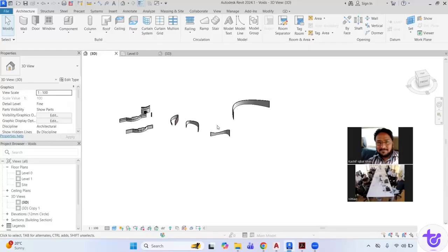It depends on the geometry which we are creating. Maybe, for example, if we have an arc, and that arc is start, end, and center, 3-point based. So it is better to make it a 3-point. But if there is a shape which has different curvatures, maybe a complex geometry, then as per our requirement, we have to increase more points, because more points you have in an adaptive family.